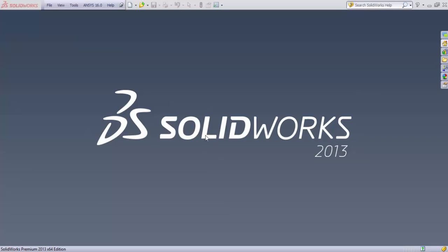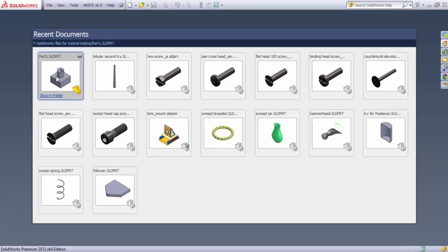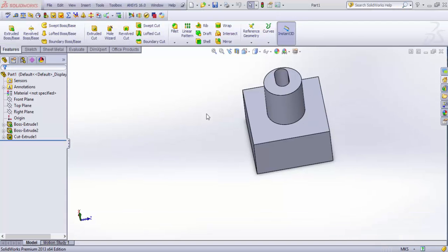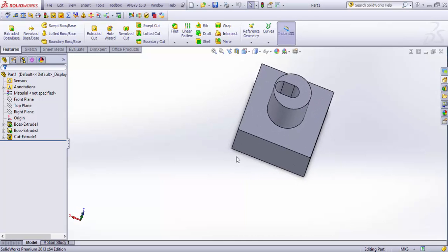These are basic machining operations primarily done for reducing the stress concentrations on any kind of machine parts. So just jump into the previous example that we have seen before. Press R on our keyboard, and this is the part that we had created before in our starting tutorial, and this would be a very good example for showing nearly all the features associated with the fillet feature.